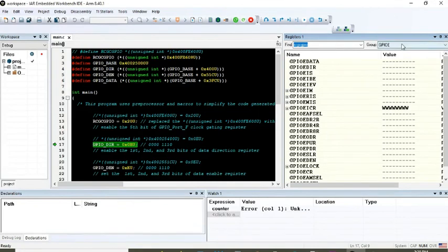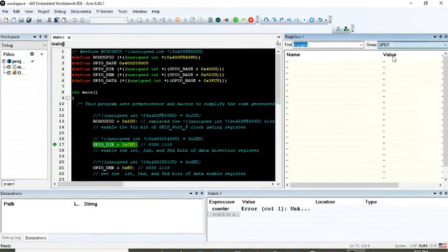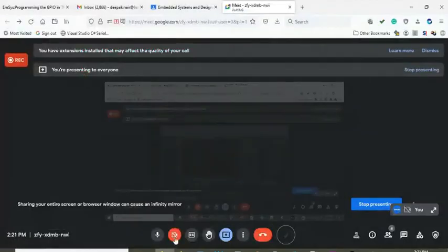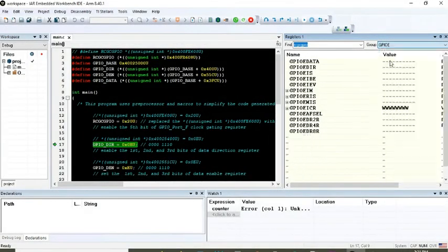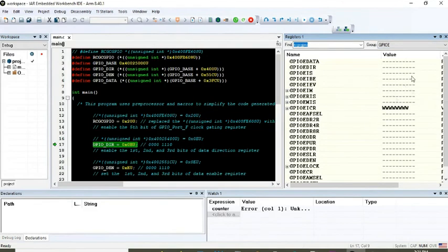What is it signifying here? Why are the registers of GPIO port E with these blank dash lines? What is the significance? What happened? What are these particular lines signifying? Whereas it is not there in GPIO port F. Okay, why? Can you correlate something? Here there is no clock provided, so they are all disabled.